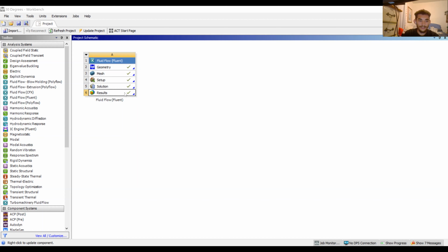Our location is symmetry 1 because it's our top face, and then the variable that we're using, remember, these are velocity contours, so we want to use velocity, and we're going to keep the range local. Like I said, you can put whatever amount of contours you want, but 50 was reasonable for this specific application. So you hit apply, and this is what your velocity contours for this specific 30-degree angle and specifications is going to be.